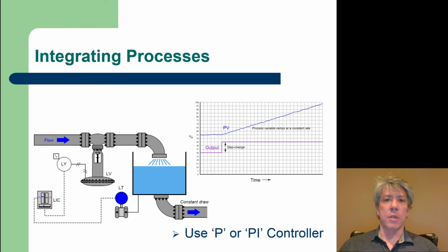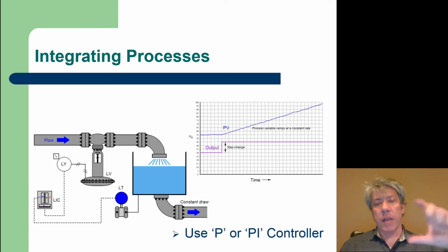With this type of system, you can simply use a proportional controller and it will work, because the natural integrating action takes care of essentially mathematically what you would need as an integral action in the controller. But if you think about the proportional action, it'll make sense, because if, let's say, the level in the tank is at 10 feet, we want it at 20 feet, okay? That's an error of 10 feet.